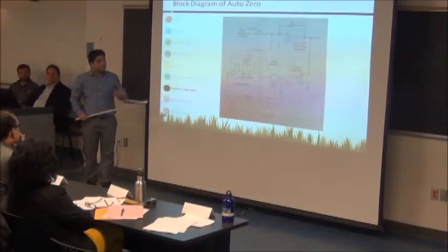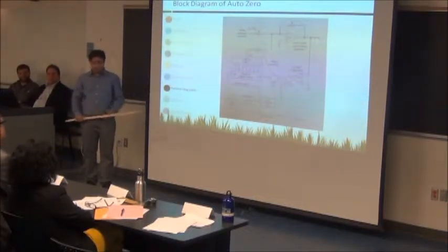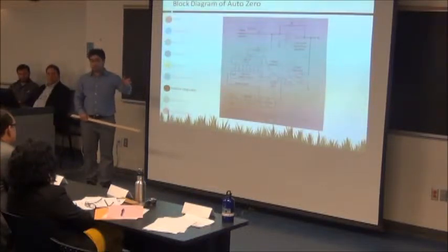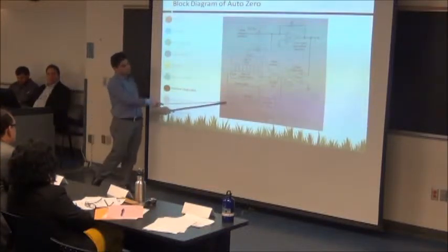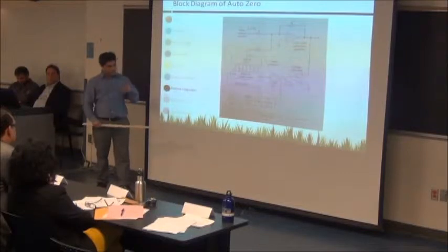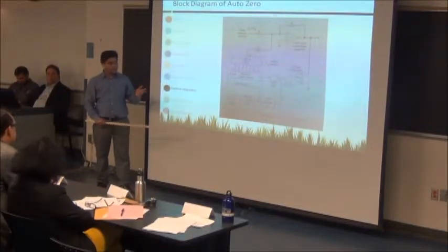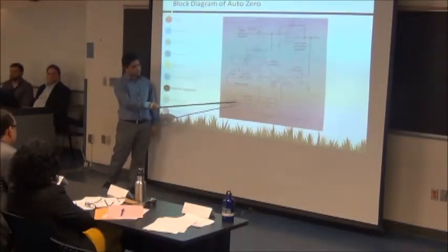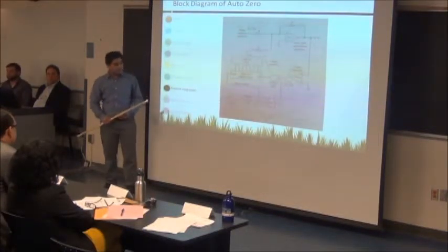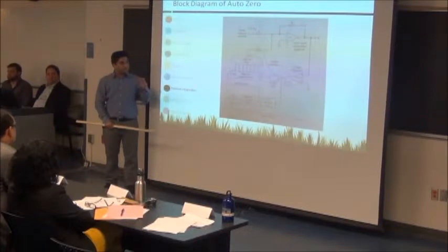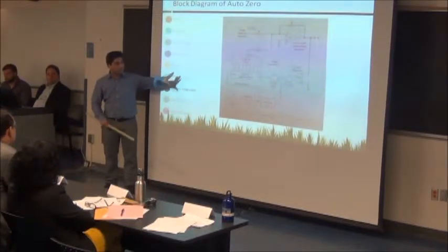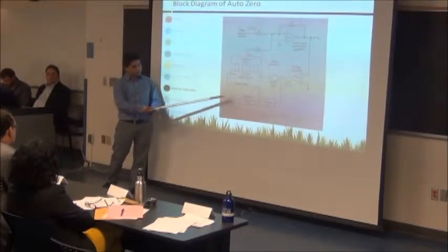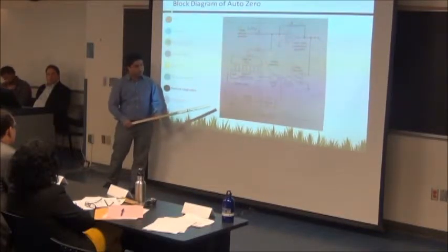Once we press the zero from the patient simulator, then we press the zero button from the front panel control, which is this switch here, and that push button will trigger the first shot here, and that first shot of 1 second will reset the whole counter circuit, and also trigger the second shot,